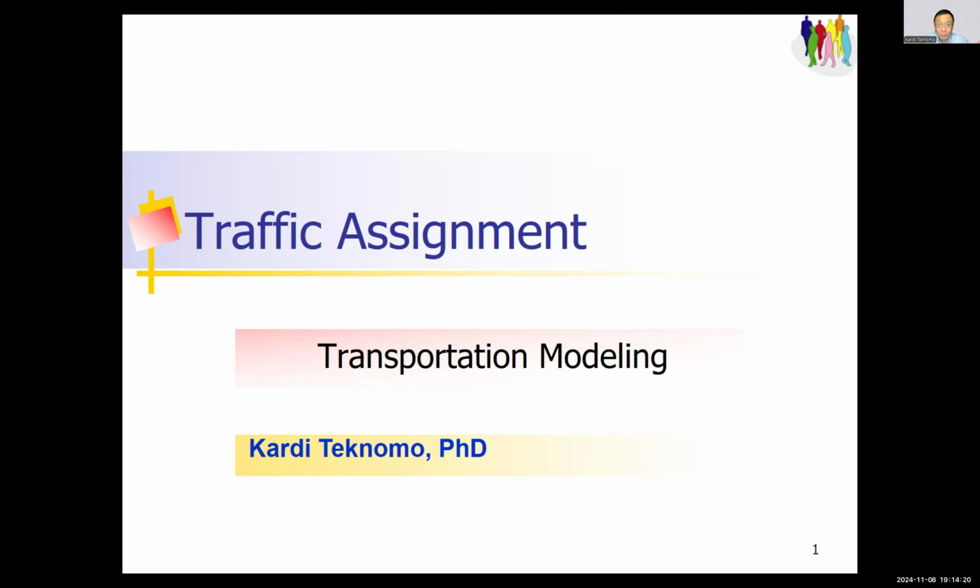In mode choice, a while ago, for each cell in that trip distribution, now you want to assign what mode they will use. Either they use car or bus, they use bike, or they are just pedestrian. So you can start to get the T_ijm, where T is trips from zone i to zone j, which is just one cell, and then you divide into what mode of transportation they use.